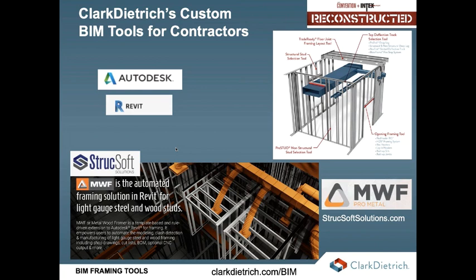So on top of that, you've got to have a small add-on or a large add-on that has a lot of detailed information about cold form steel or wood or whatever system you're trying to do. We're using StructSoft, MWF it's called. And what this does is it has great add-ons into Revit that you could walk through your project, use your wall types we talked about, start adding other trades into it, and with their clash detection systems, it'll actually say, hey, this is hitting these studs. So do you want to make a box around this, or do you want to make an opening around this? What type of tolerance do you want to make this opening?